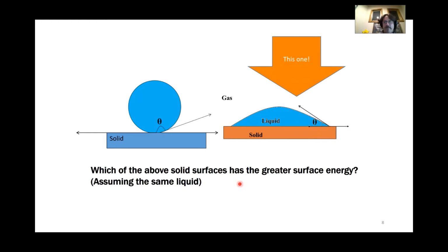So it's a little bit opposite. The solid surface with the greater surface energy has better wetting. That's actually pretty interesting. A good analogy is if you've ever glued two pipes together, and I think the person who told me this was Bradley, so I have to give credit to the Brad man. When you're gluing two PVC pipes together, you want to essentially sand one of them, so you're effectively increasing the surface energy so the glue actually wets better.